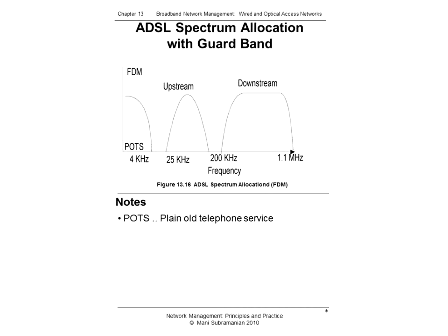So there are two schemes for separating the upstream and downstream frequency band, and that we call as frequency division multiplexing, that is FDM. So in FDM, actually, after separating the upstream and downstream bands, each band is divided into one or more high-speed channels and one or more low-speed channels.